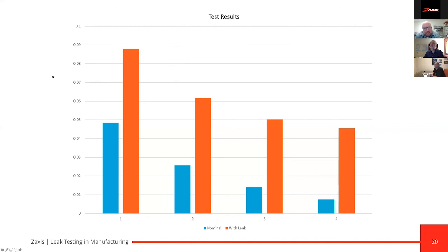but it's well beyond what you're going to be using as far as a leak rate. Like Don says, we typically say, good part, bad part should be in that second or third digit for a greater repeatability and greater sensitivity, because of what could happen externally, because of part heating, part cooling, part manipulation. Let's say an operator bumped the part while it was testing and changed the volume. That will all affect the test while it's testing.